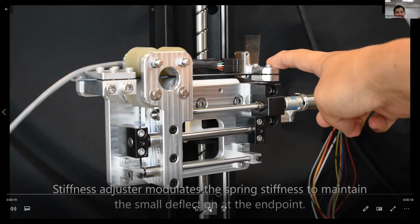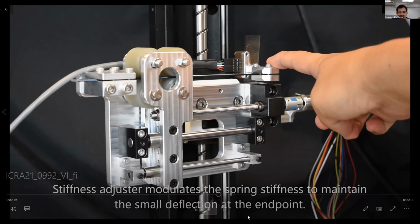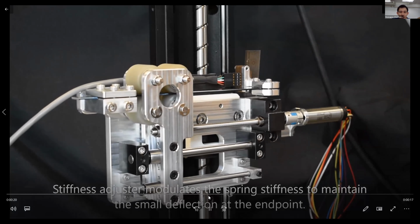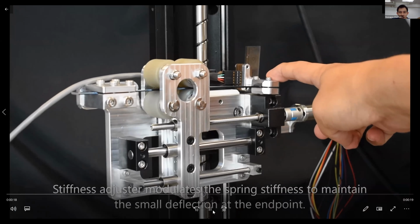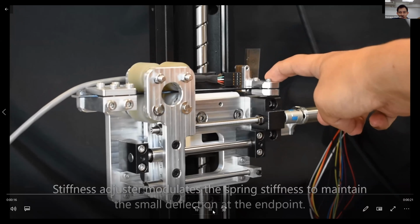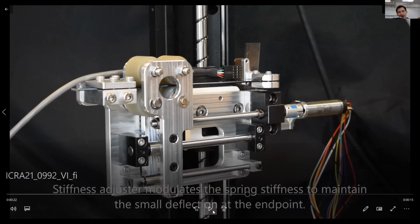If the ruler is long, you can easily bend it. But when you move the support position close to the applied force position, the stiffness at the endpoint will increase. So what we do here is we try to limit the deformation at the endpoint.